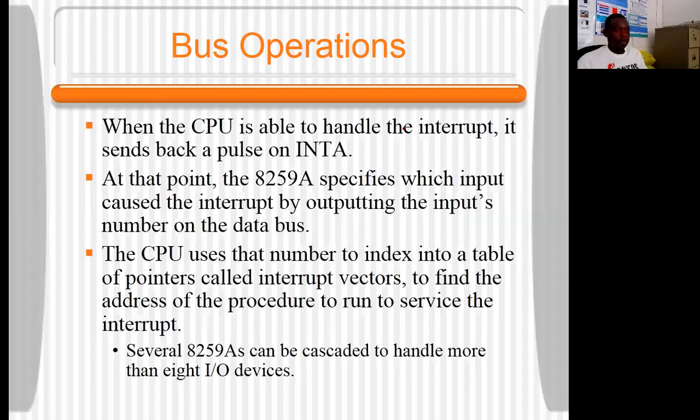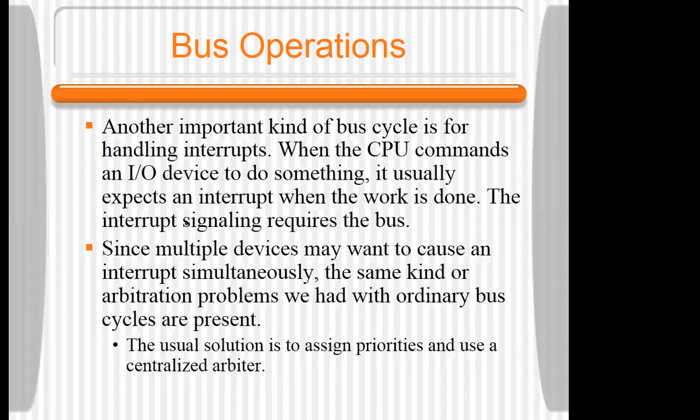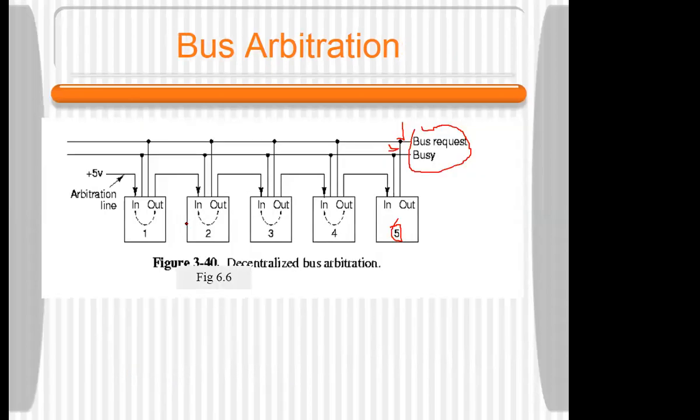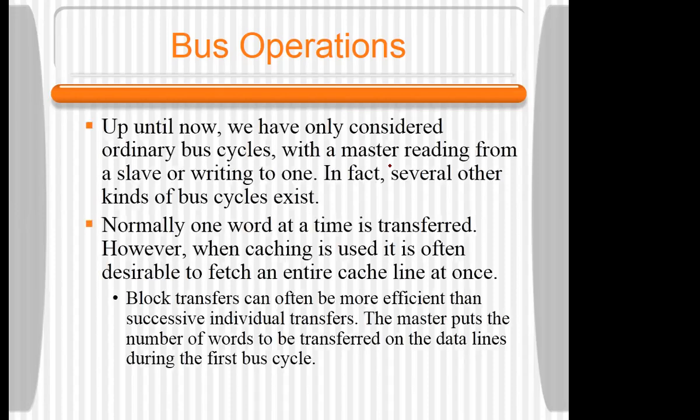Right, so we had ended our discussion on bus operations. So if we wait for others to come in, we can just make a rerun of the bus operations. So we're saying in bus arbitration, there will be a request issued by a device. Then the arbiter will check the request and see if there is no other device using that bus. Then after that, you can proceed to allocate it time to use the bus, right?